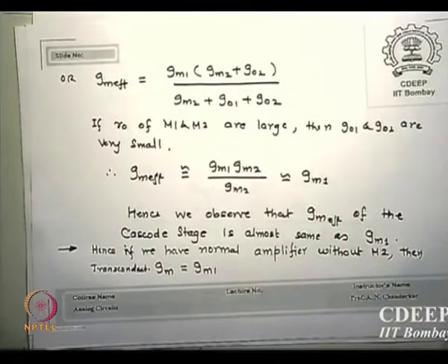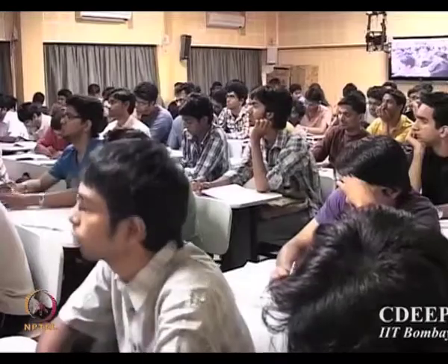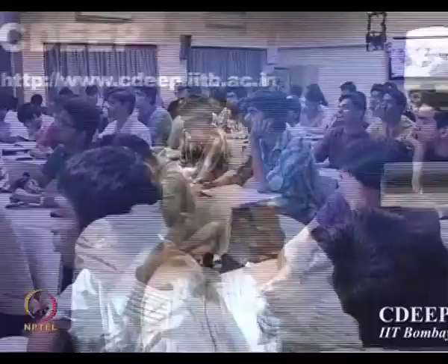Now typically lambda of the transistor is how much? Close to 0.001 or 0.002, or close to 0. So R0 is normally infinite, or even if it is finite, mega ohms, tens of mega ohms, at least a mega ohm. Is that correct? Unless your current is very, very high, R0 cannot be reduced to kilo ohms. If it is very high current, then the power will actually take care of your device failures, so you don't worry about that.